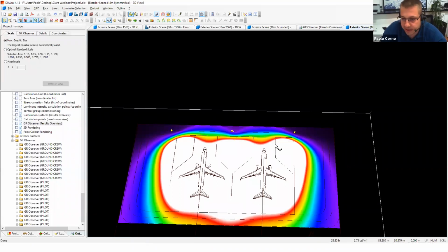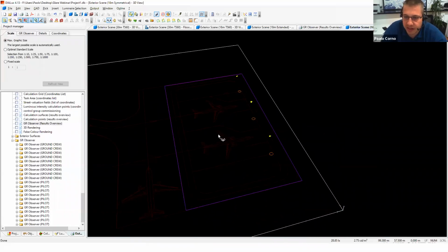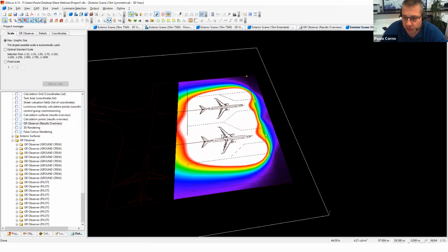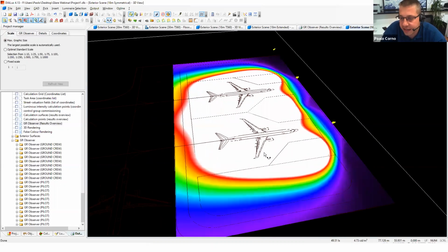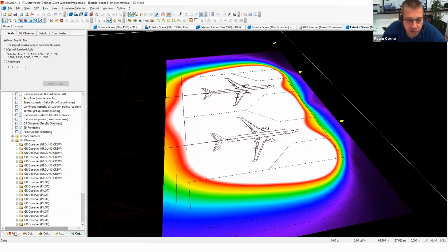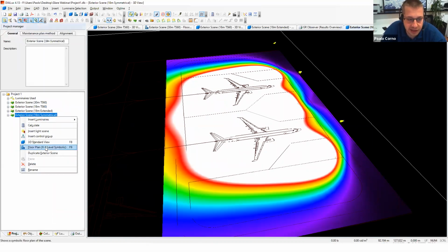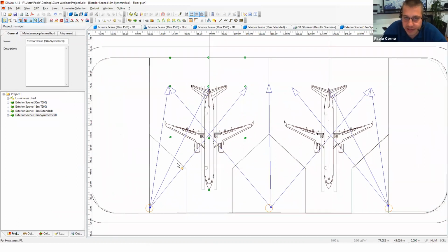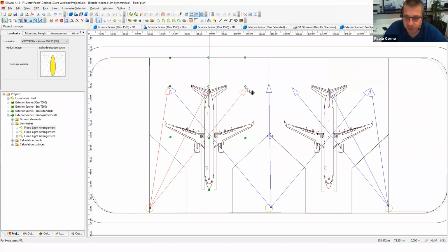Sometimes, of course, due to the geometry of an area, you're left with no other option than using symmetric optics. In that case, to mitigate the glare as much as you can, you identify, for example here, the central area of the fuselage where I know the pilot will sit at every spot while moving, and you always try to avoid having direct beams going onto this line.